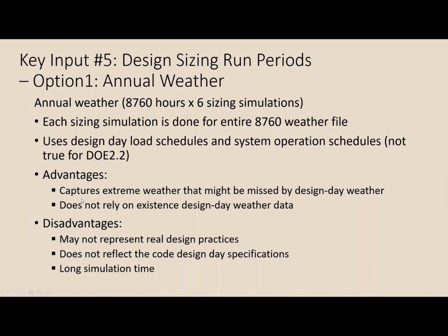The alternative is to use design day weather. But some advantages of using actual weather are that if your design day weather doesn't quite capture the extreme weather that's in your weather file, then you may have some issues with not meeting loads that are confusing. And if for some reason you're having trouble finding design day weather that matches your weather location, this is an easy backup to that problem.